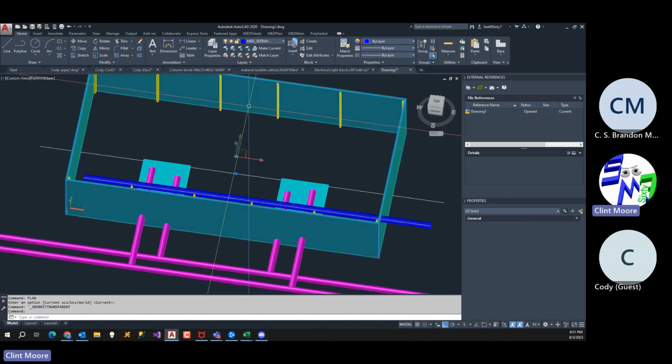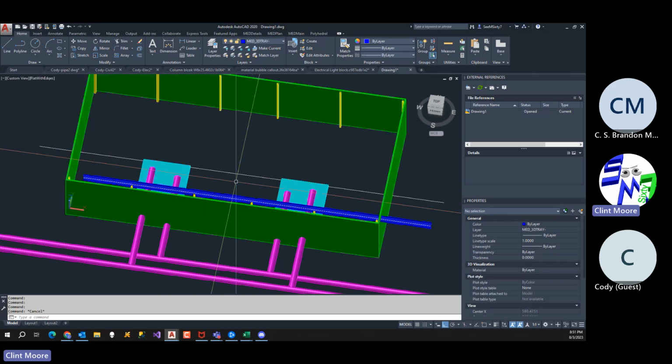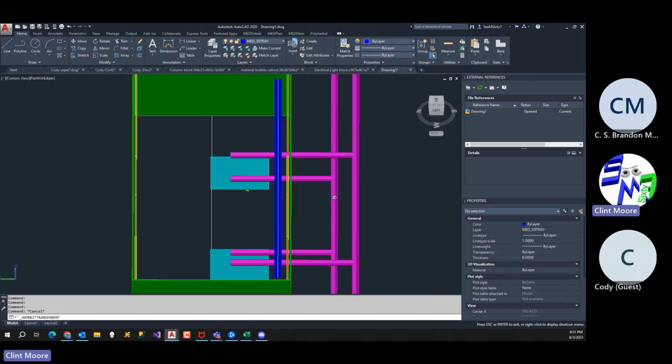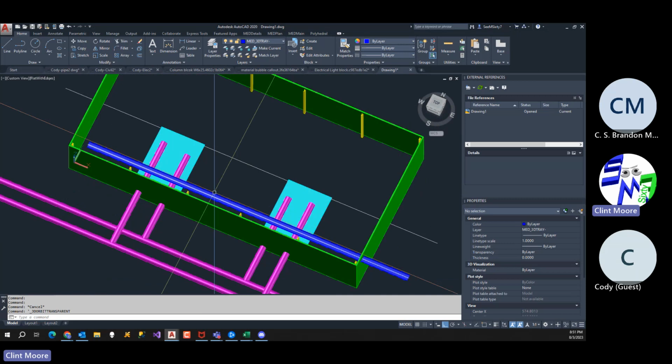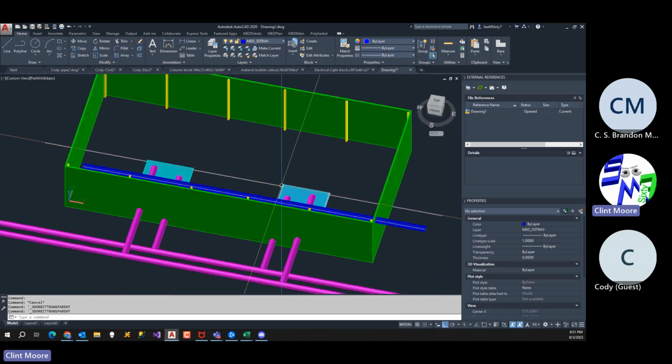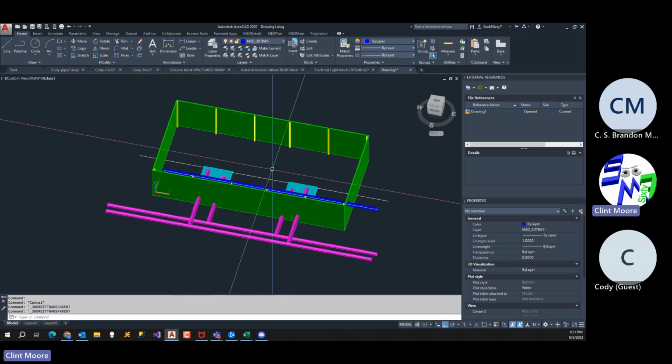Structural will typically take care of this, the building, the steel, and these foundation pads right here, because structural takes care of steel, concrete, dirt work, and things like that. All right. Civil structural is typically what the discipline is actually called. So what I'm going to do is break these into individual models, because right now we have everything in one file. If structural wants to come in here and work on this file, they can't because I'm in it. So typically each group works on their own files, and you create a file that combines them all together via Xrefs.